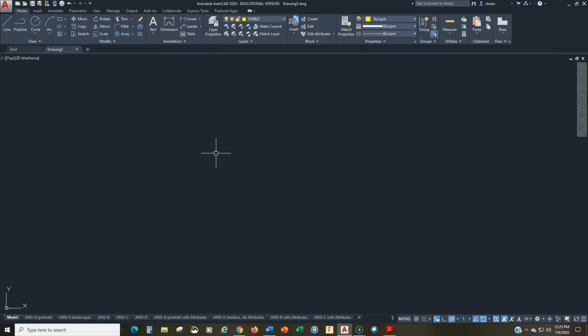Now, the units are the way that we interact with AutoCAD when we put in numbers. So when we're drawing a line, let me show you this. When we draw a line, and we want to draw a line that is, let's say, 7 inches long, and you've been doing this all class, notice that the number up there, 5.479, is highlighted in blue. If I type in 7 and hit enter, it draws a line that is 7 units long.